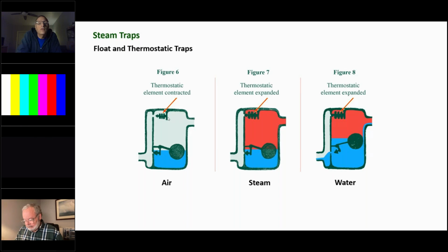But when you convert to a pumped system, you can't have that steam coming back to your boiler feed tank. Excuse me. So you have to trap the ends of the mains when you're converting from gravity to a pumped return. So on like an LGB boiler, we put a Hoffman VBF boiler feed unit in there. We would have to put that boiler feed unit in to collect the condensate, because if all the condensate would go back to the smaller steam chest LGB, it would flood the boiler.